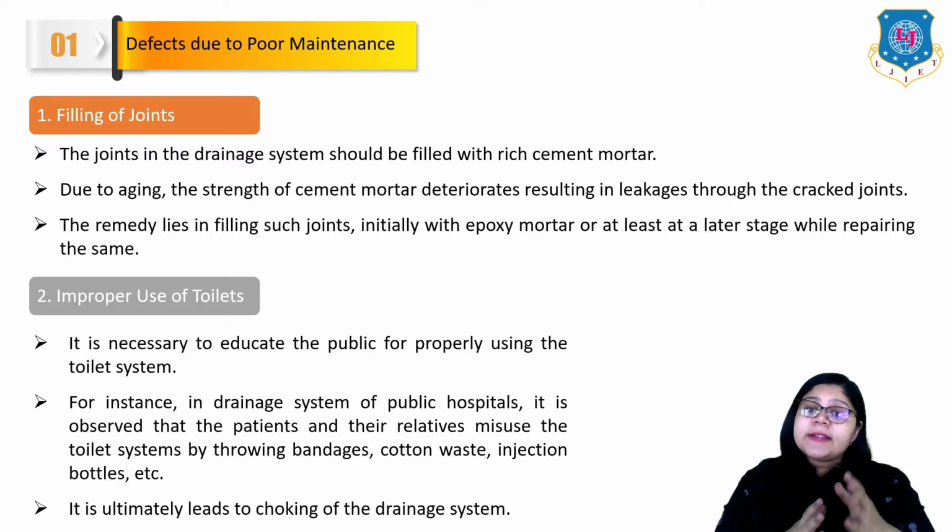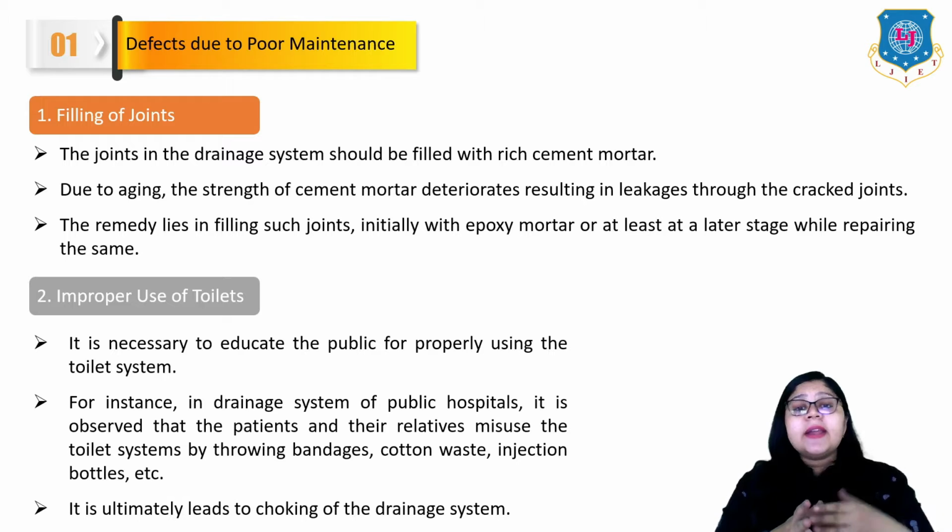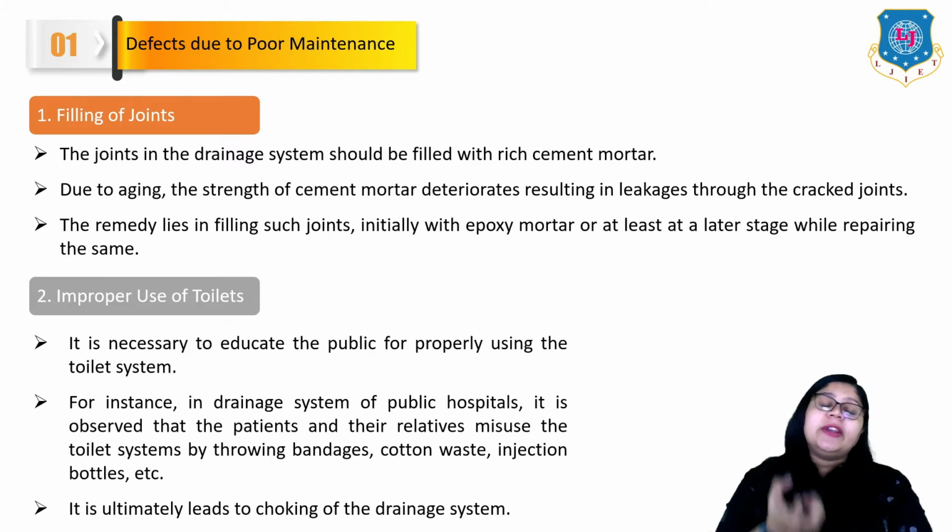It means it is necessary to educate the public for properly using the toilet system. For instance, in the drainage system of public hospitals, it is observed that the patients and their relatives misuse the toilet systems by throwing bandages, cotton waste, injection bottles, etc. It ultimately leads to choking of the drainage system.